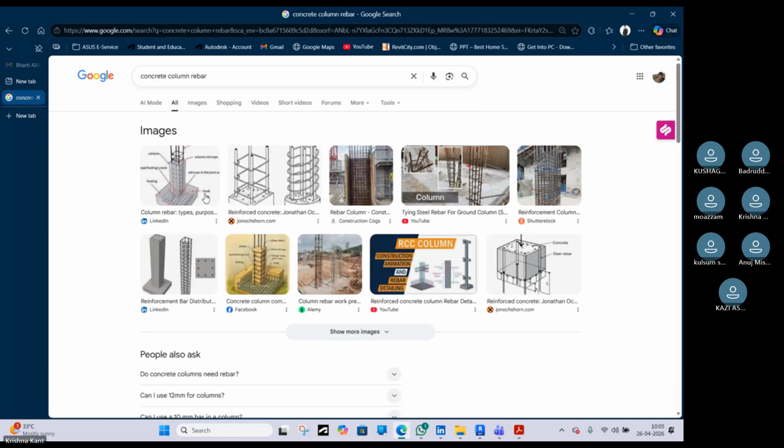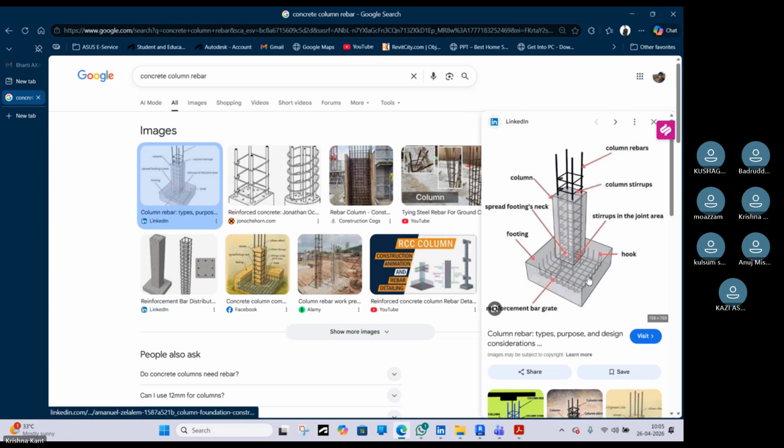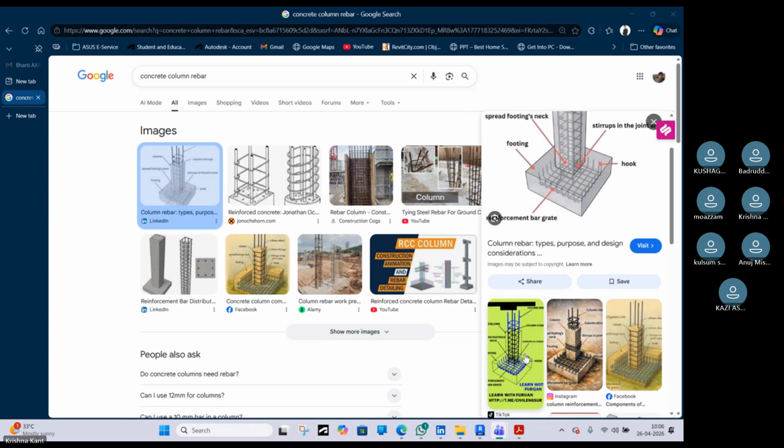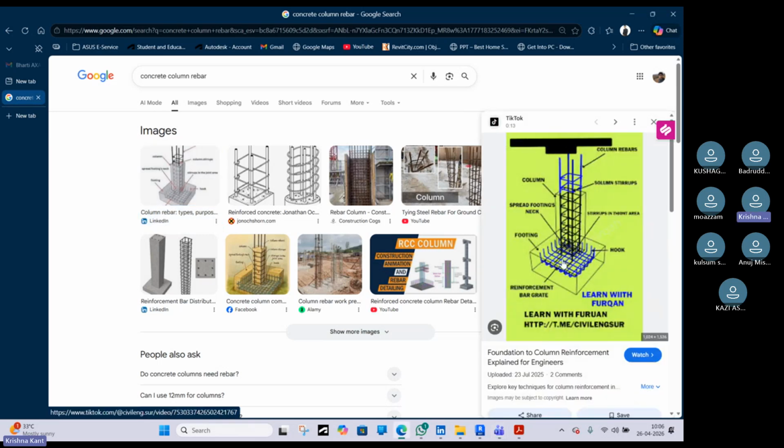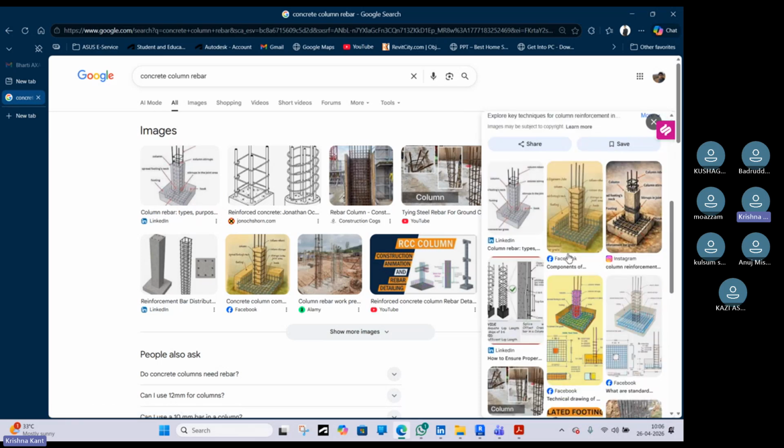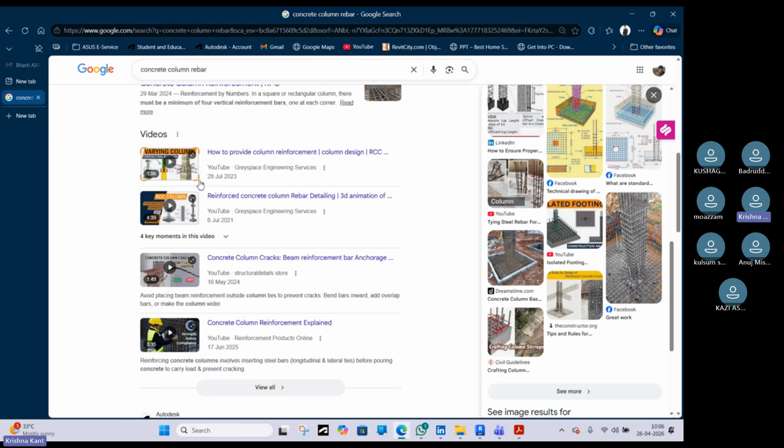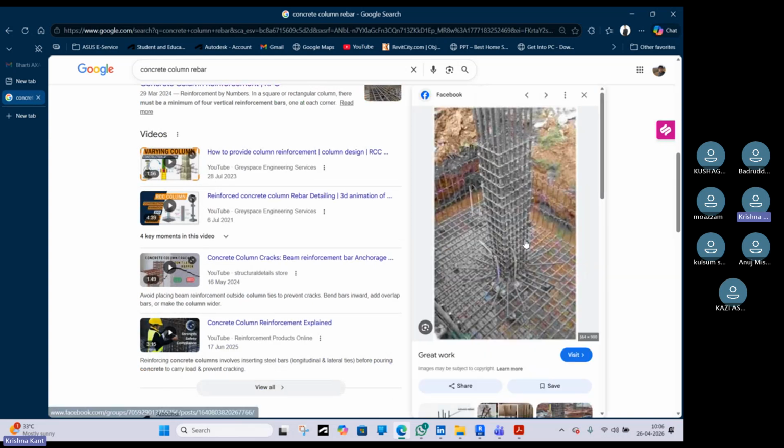If you can see the image, the vertical member is going throughout the column and stays on the footing bottom reinforcement. So basically we have to bend the vertical member at the very end, and we have to bend around 300 mm. Yes, this is a good prime example. All the vertical members are well inside the concrete column footing, and then you have to bend.